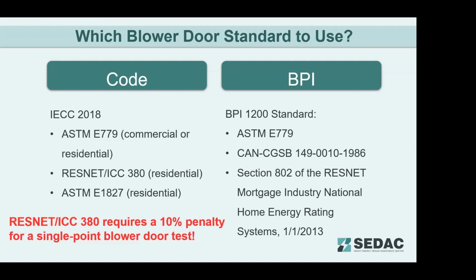No matter what standard you're using, these are very similar standards. If you dive into the fine details of it, they are very, very close. I'd hesitate to put a percent on it. 95, 98% similarities between them. And I'm sure somebody will argue with me on the point. There's probably some big differences somewhere, but I would note that the ResNet ICC 380 actually has a 10% penalty for using a single point blower door test. We're going to talk about the difference between single point and multi-point here in a minute.